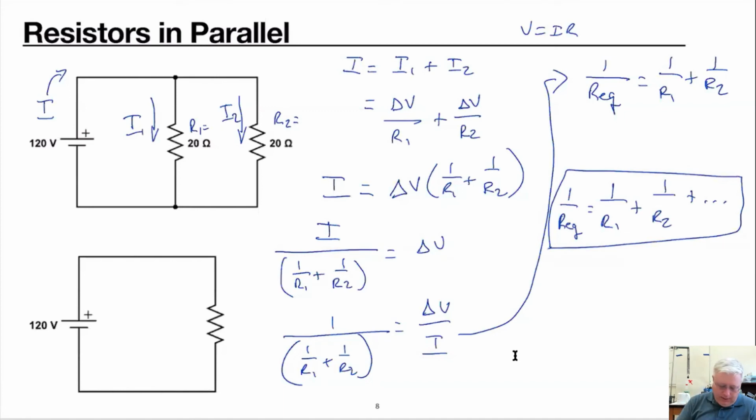And so we could likewise do the same thing. Find the equivalent resistance, put one resistor in there with that amount of resistance, and we'll get the same effect. Okay, so it just depends on what you're trying to do, what electronic equipment you might have available at the time.